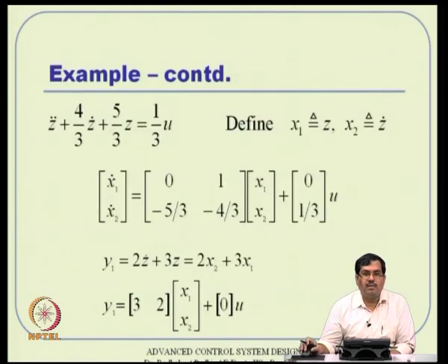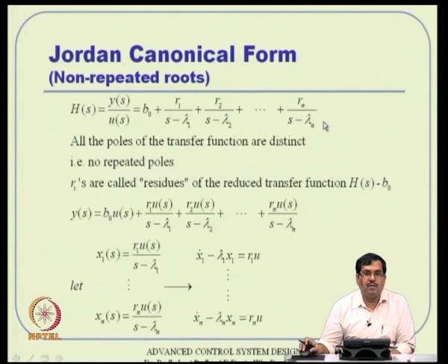For example, if this is a spring mass damper system, then z is nothing but position, this is velocity. So, that definition is intact in your state variable. Now, in this form, x 1 comes through this entire polynomial, x 2 comes through that actually. So, the definition of state variables no longer has a direct physical meaning in the system dynamic equations. Okay.